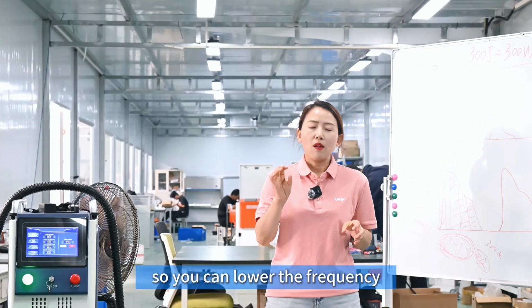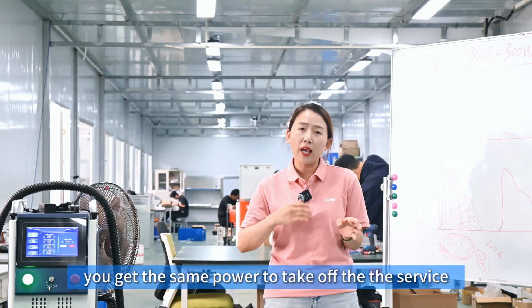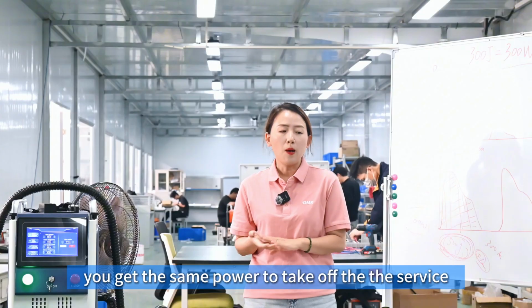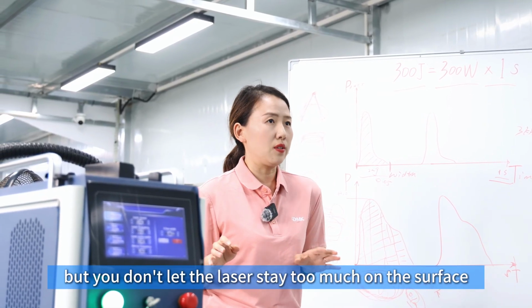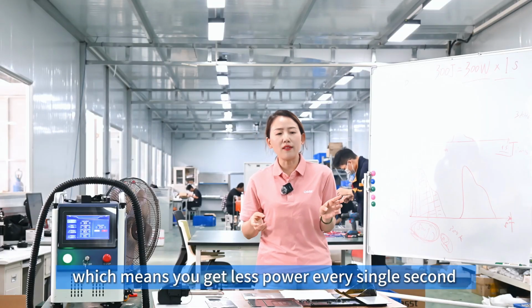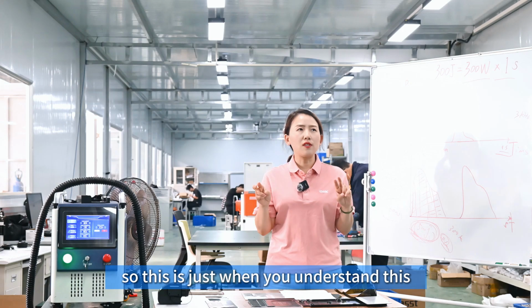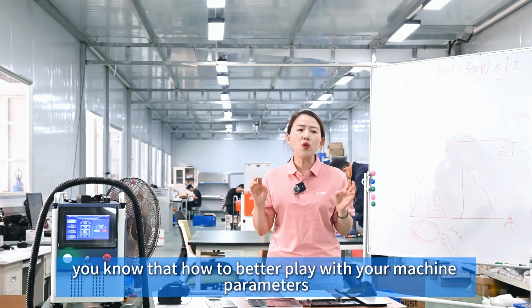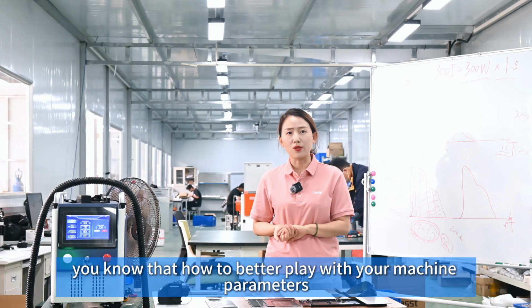You can adjust a little bit the peak power of every single pulse. So you can lower the frequency. You get the same power to take off the surface, but you don't let the laser stay too much on the surface, which means you get less power every single second. When you understand this, you know how to better play with your machine parameters.